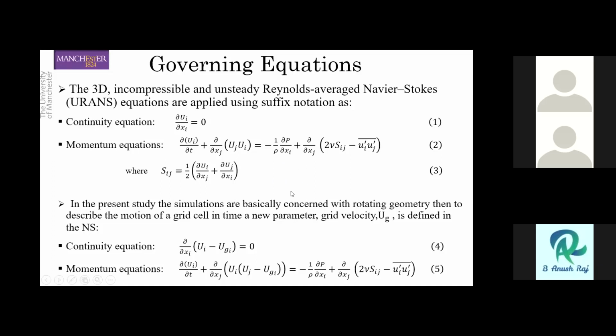In the present study, simulations are basically concerned with rotating. Therefore, it is important to add a term of grid velocity to the continuity equation and the momentum equation in order to account for the rotating in the cylindrical part for the blade.